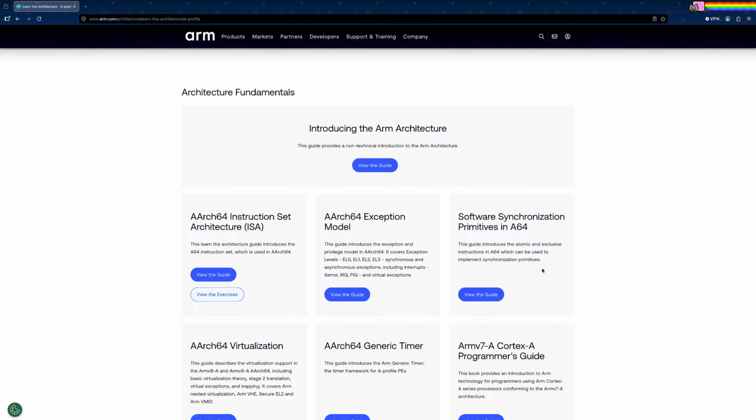As part of that process, I have been building a bare metal kernel from scratch in C and assembly, of course. Along the way, I learned a lot about exception levels, boot flow, exception vectors, interrupt controllers, and various other subsystems of an operating system required to bring up a system from bare metal.